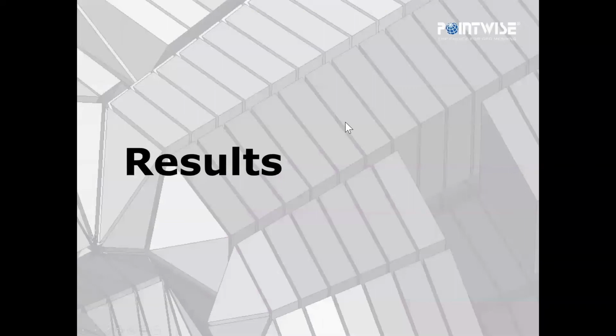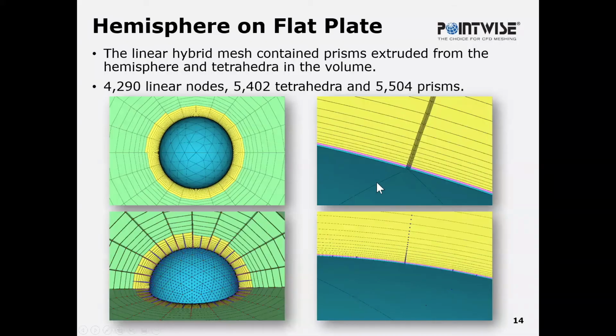So let's look at some examples. Initially, the examples used in development of this approach are quite simple. This is a hemisphere on a flat plate, and the wall surface on the hemisphere has a triangle surface mesh that is grown out, growing layers of triprisms until they become isotropic, and then outside the last layer to the far field there will be tetrahedrons.